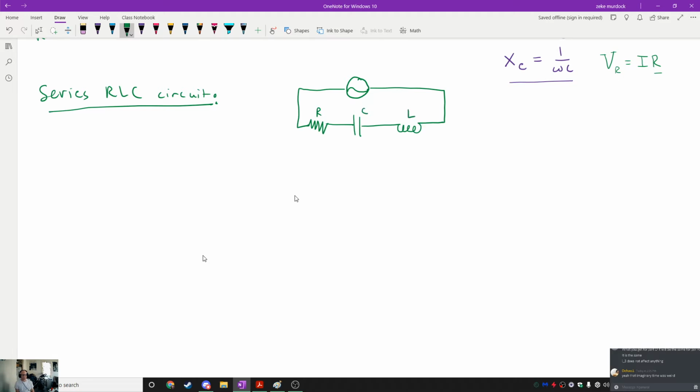Okay. The next thing we're going to do is, on our picture right here, I'm going to put little voltmeters. So this is going to be V sub R. That's going to vary as a function of time. We're going to have another voltmeter for here. This will be V_C, and this will be V_L. So we're basically just putting infinite impedance voltmeters, or infinite resistance voltmeters, that are not going to change our circuit in any way. The idea is they have a huge amount of resistance, which means that any current flowing in our circuit...